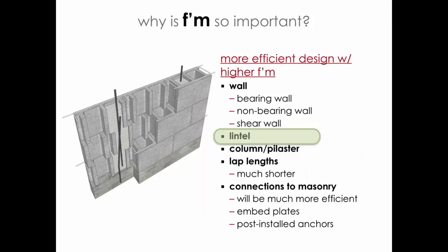We have to know what the strength is so that we don't have all 4-course lintels or 6-course lintels. When I'm talking about masonry lintels, I'm talking about 8 inches, 16 inches deep. They don't have to be very, very deep lintels when we use the right F'm.